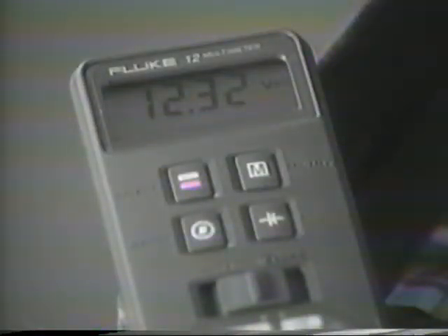Now turn the ignition on. We should get within 0.6 of a volt of battery voltage. If the voltage isn't correct, the troubleshooting guide recommends a repair procedure. Again, we're okay here, so we'll go on to measure the grounds. If the ground connector gets loose and gets high resistance, you can get system problems because you lose power. That's why you should always check the ground too.